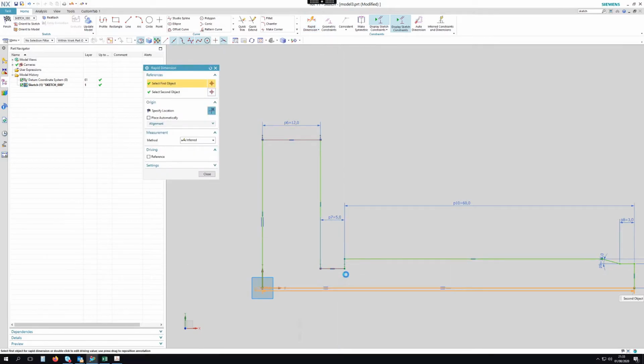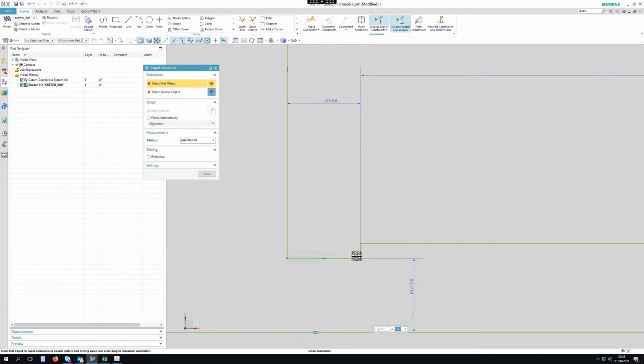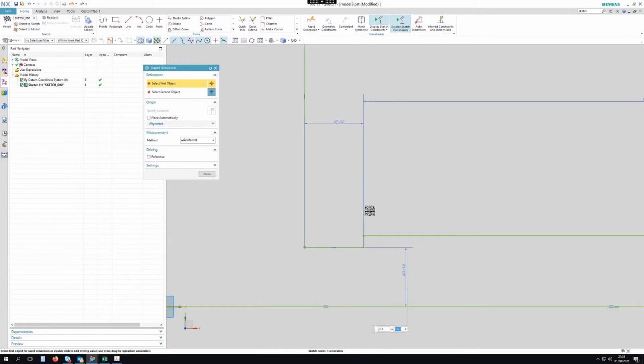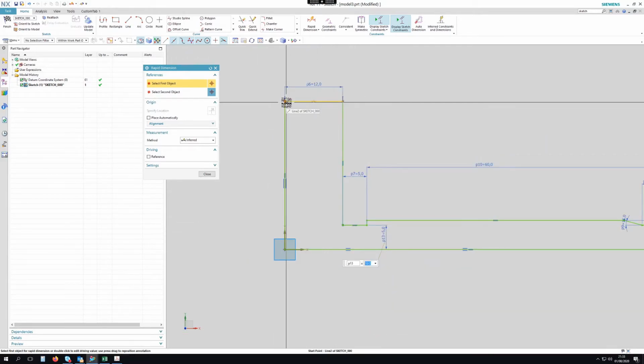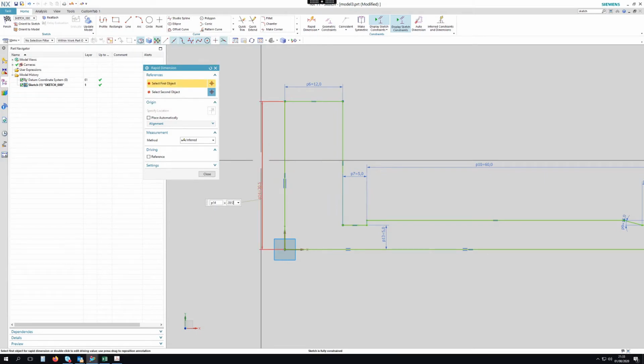Let's go from there to there. And let's make this, it was M12, so make this down to 10 divided by 2. Tapping drill is 10.25. So the underside of the thread should just miss that diameter, so we can screw cut it into that thread. Let's go from there to there. Let's make that 20 divided by 2.